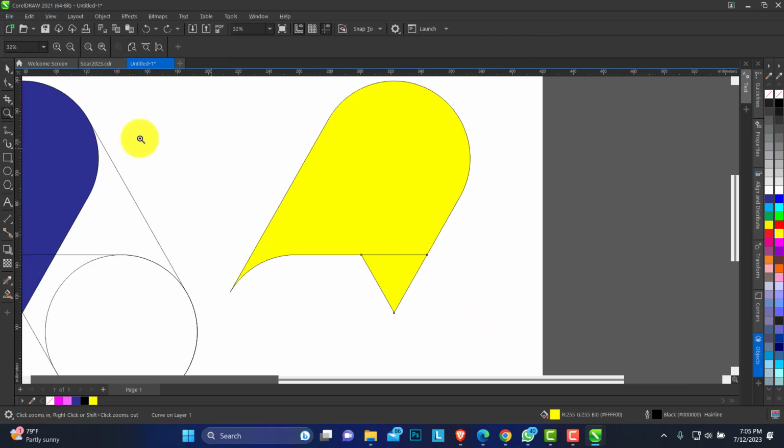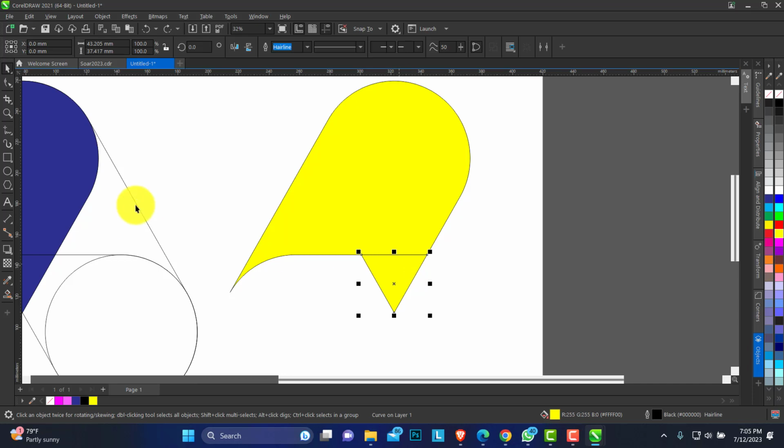Okay, so you can zoom in a little bit with any of the freehand tools. While you're moving on the edge, you see it tells you on the edge. When it says midpoint, you click and align it to this. So do the same thing for this area. Okay, so this is the midpoint. With this, we have defined the center of this circle. So you can click and drag to select all of them and group. Now we change this triangle point, so this is the center.